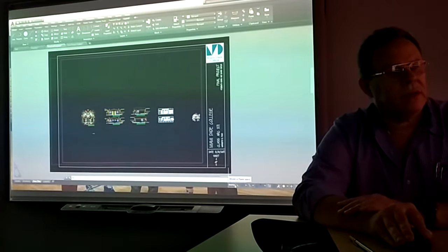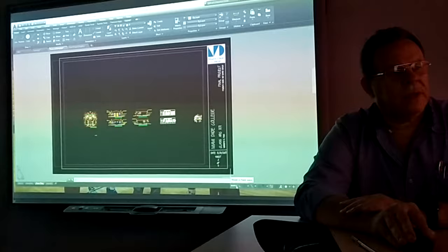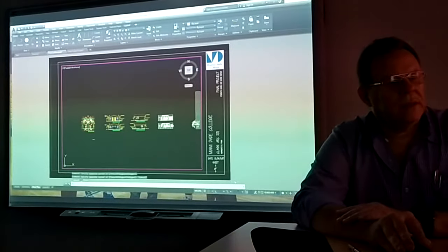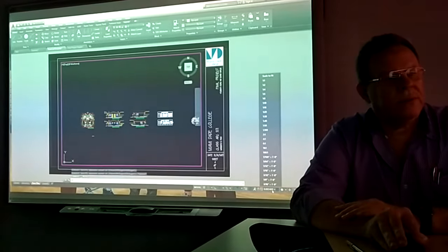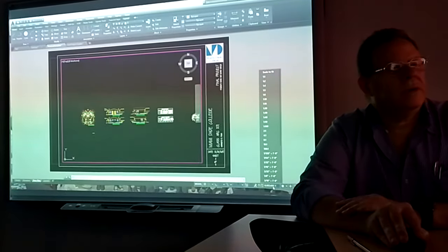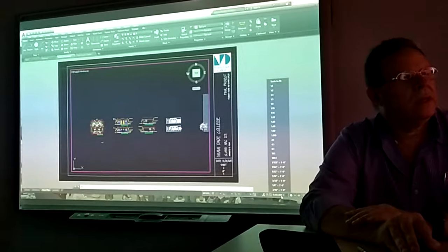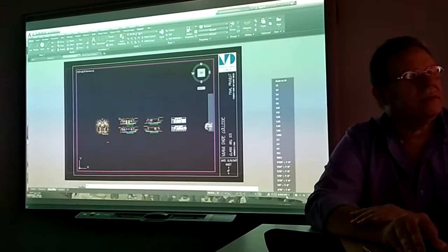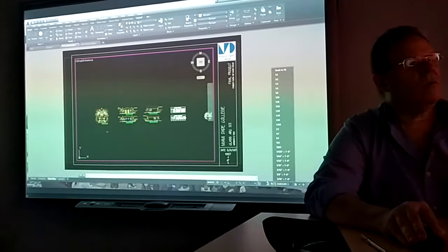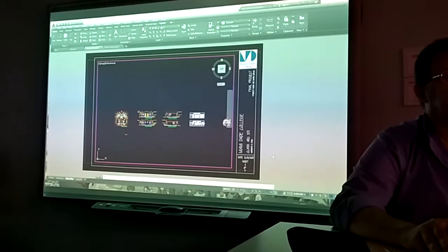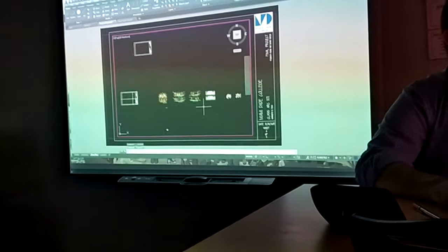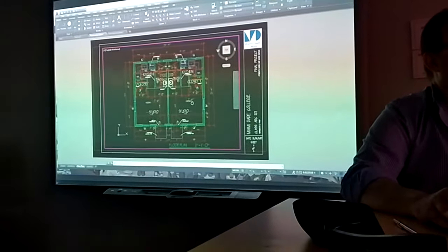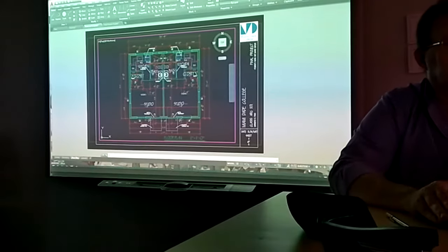You could either do it here too. Okay, so let's activate it. Now this tab here, you could set up the scale that you want. I want my floor plan maybe 3/16. All right. So what I basically do, just to make it easier, so they don't disappear, I zoom in and I try to put the floor plan close and play with the scales.